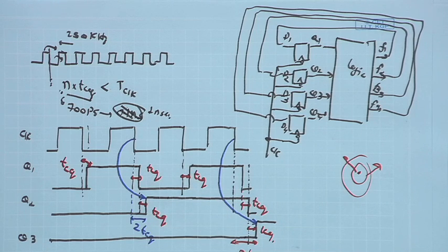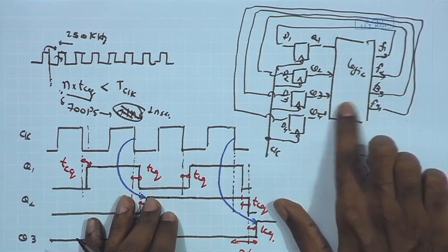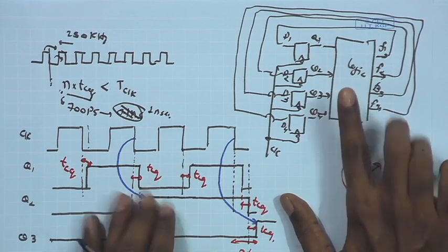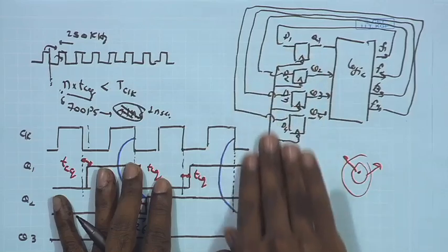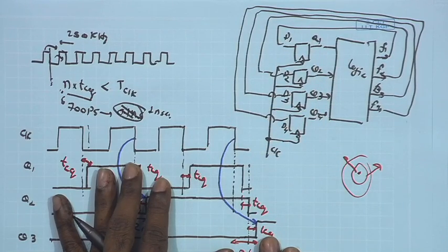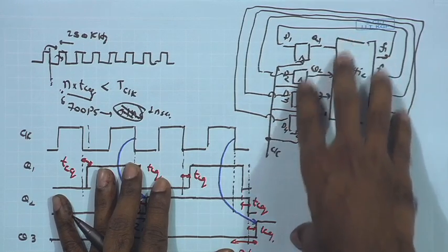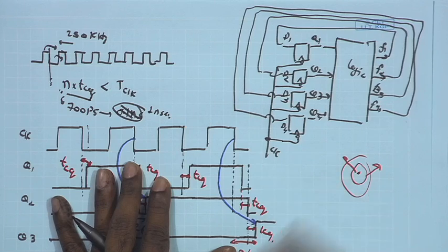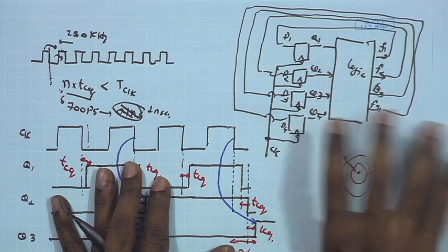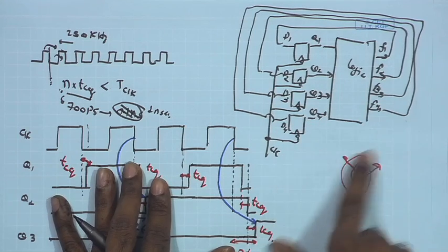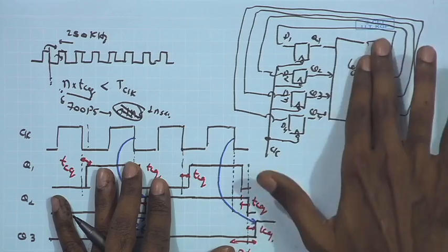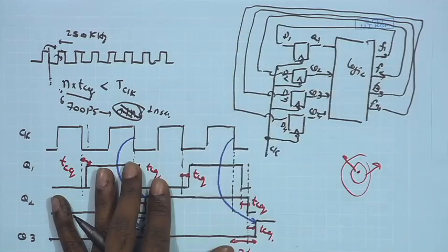It can be suitable for high speed application. Here the delay of course is going to be constrained by this logic. So, logic also has its delay, and if you are going on increasing the number of flip flops, the logic is also going to become more complicated, and there we have to make sure that the logic delay is also within limit, and making sure that it is able to compute this f1, f2, f3, f4 before the next edge of the flip flop.